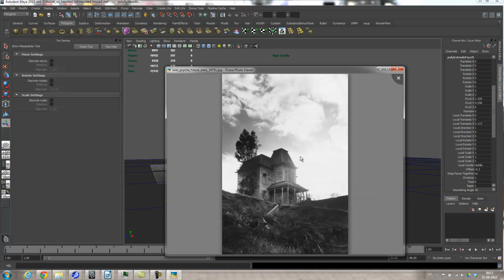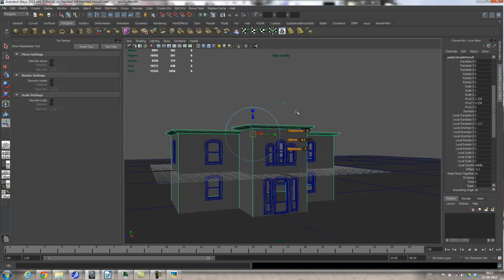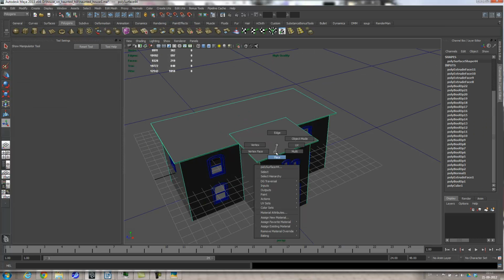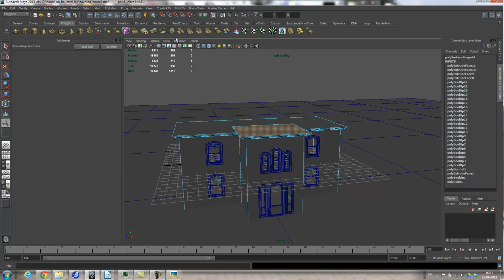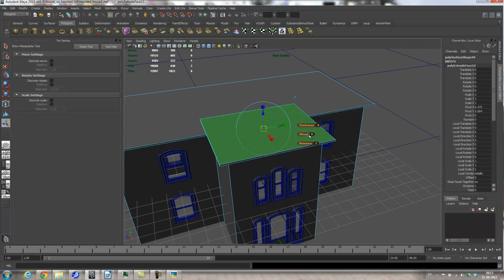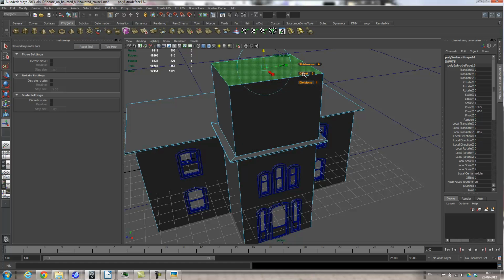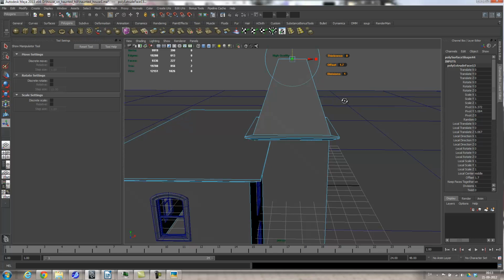So let's see if we can get one from the side. So you can see essentially these are more or less symmetrical. So these are just like going up, and this is going up too. So I'll just do these two inside each other. So I'll just grab this one first, face, grab this one, do the extrude, offset this in a little bit, like I think it's like there maybe, and then do the G key to repeat, and then pull this up, and then pull it in like, I think it's somewhat like this.